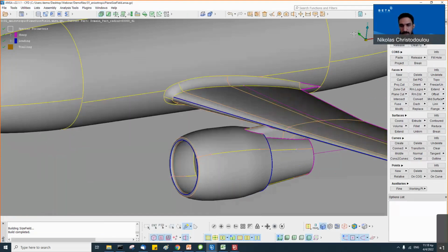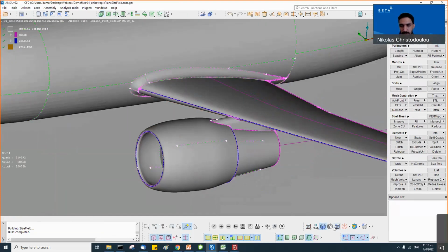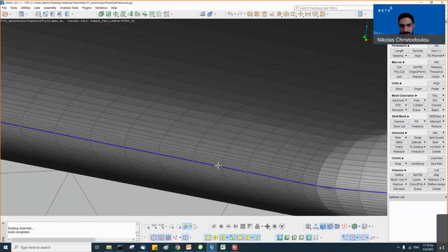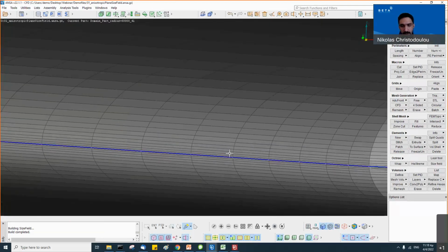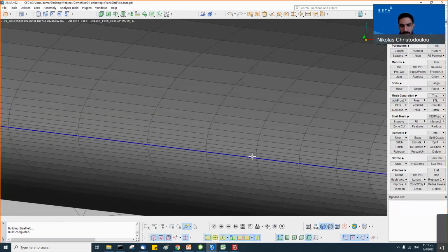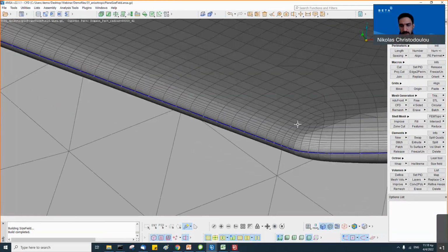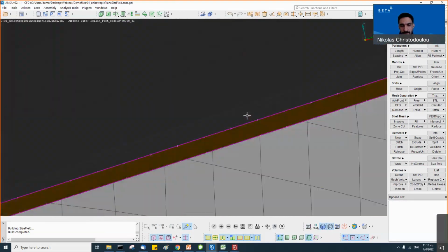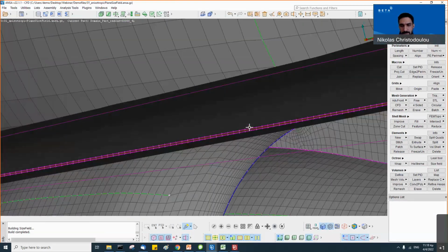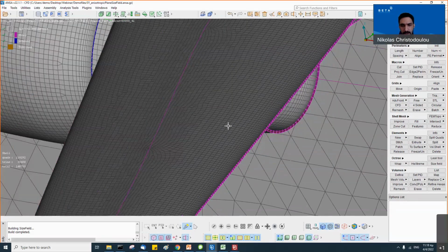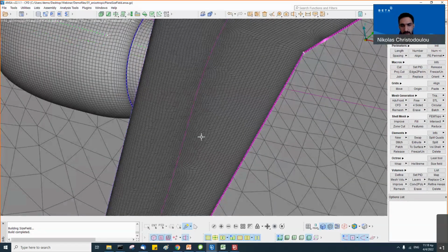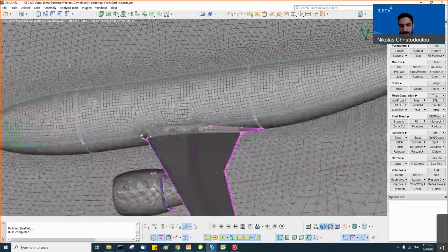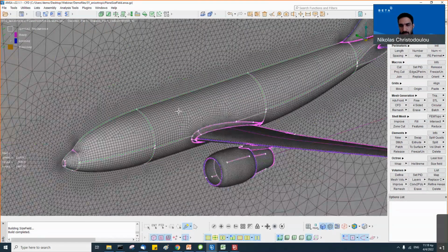And this is visible if we see the mesh. And you can see now how nice the leading edge is resolved using zones and quad elements. And the same stands for the trailing edge. You can see how nicely it will blend with the rest of the mesh, and the mixed mesh type can work very nicely and be oriented to the fluid flow.